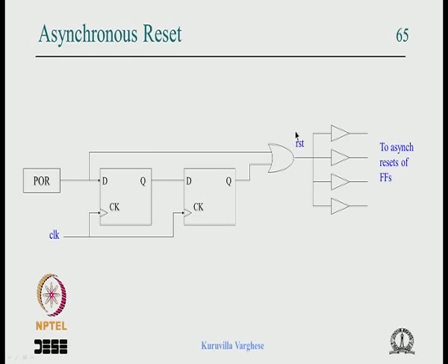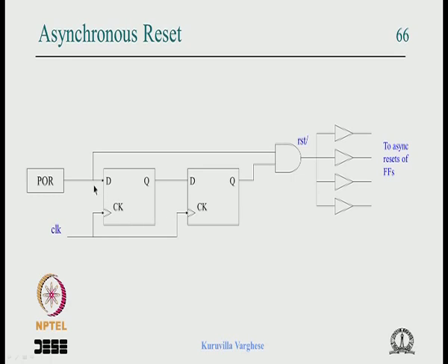Now for the active low signal, it goes in the opposite direction: it is 1, then goes to 0, and comes back to 1. So we replace this OR gate with an AND gate, and we have done it. It is a 0 and a delayed version of 0. You know that for an AND gate, if any input is 0, the output is 0.